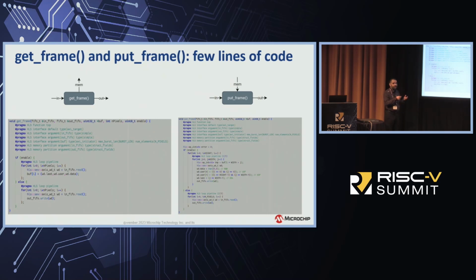The memory buffer is just a pointer, another argument to the function, which is a pre-allocated buffer by the CPU. And it's telling the module where you want the frames to be stored. Now, if this transformation is not enabled, then just read the pixels of the input stream and forward them. And this is not pseudocode. This is the entire code that you need, and it's all written in C, to create this hardware module.